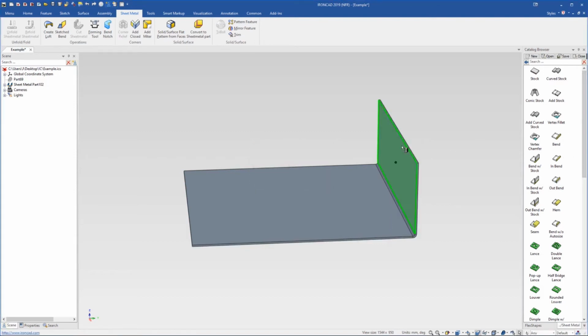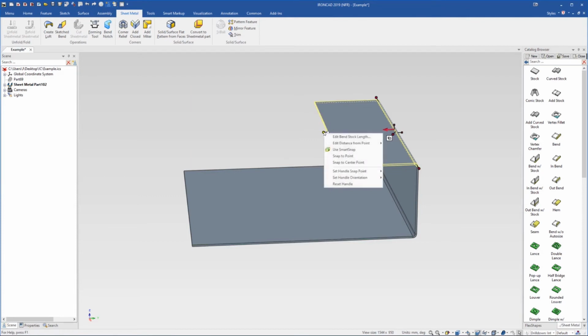And then I'll drag and drop another outbend here, and it's worth noting you don't have to drop on the exact edge. You can drop anywhere here, and it'll snap there. And you press this arrow if you'd like to flip it, or change the angle by 180 degrees. Now we'll push and pull this. We can hold down the Shift key and snap to a point like the midpoint there if we want to. Another interesting thing to know is we could, for example, snap to that midpoint and then snap to our own midpoint of our stock like that, to make it a quarter of the length.